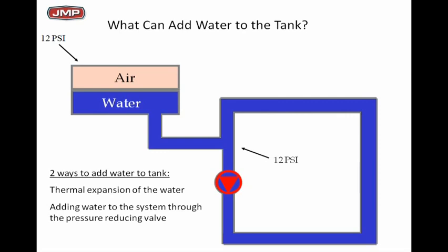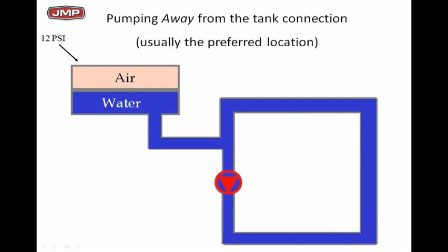So if we know that, then we can locate the expansion tank as a point of no pressure change and use that to control system pressure throughout our whole system. And most of us don't stop long enough to understand how important it is to control system pressure. And this is what this whole point is all about. So let's go a little bit further.